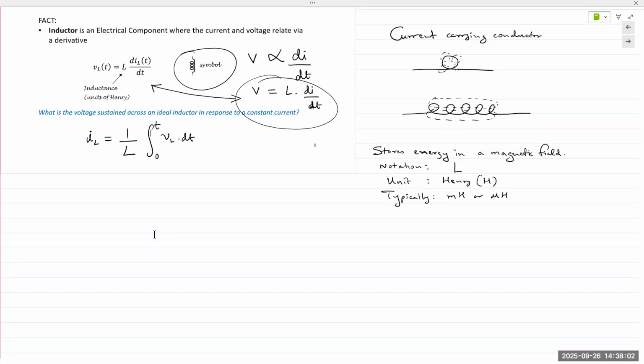If I take any of the cables that I have, if I have this USB cable here, it's supposed to just transmit voltage or current, right? Is it going to change anything if I wind it up in a loop like this? Yes and no. This is an inductor. Plus, it has current carrying conductors that are separated by insulating material, so it also is a capacitor. But you wind up a wire or a cable in a loop, it's an inductor. Okay, but the signal is still going to be transmitted. It's not going to stop.